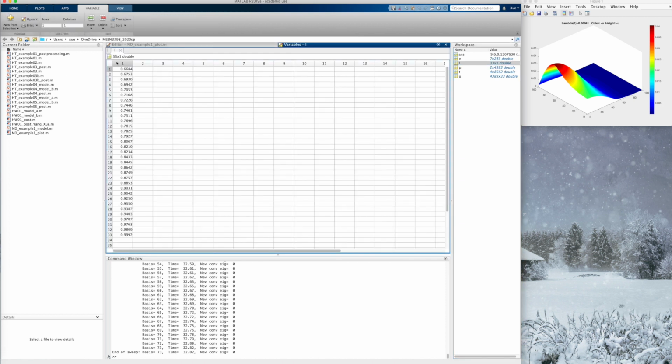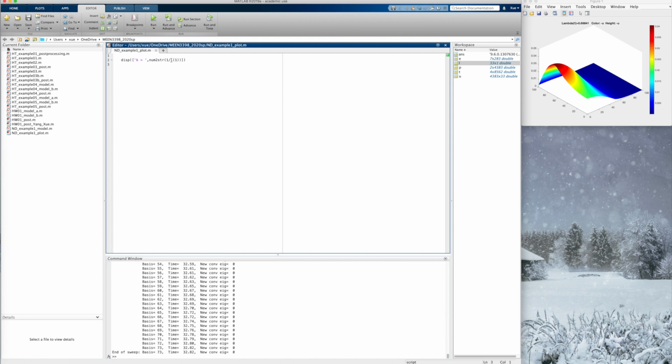It has 33 entries. It means that between 0 and 1, it found 33 eigenvalues. We only need the first one. Therefore, here I'm going to type as L1, and we run it. You see that k is equal to 1.4961. Okay, this is what we want.